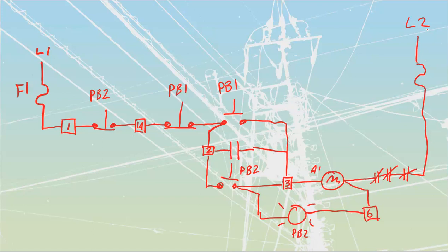We've traced it through. We've gone from component to component. What I would do now is I would say, can I neaten this thing up? What do I see that I can neaten things up? I can move some components around. I have also got a number of wires that are all considered to be the same. If I look at this on my drawing, this wire, number 3, is all considered to be the same wire, right? Doesn't go through any junctions there whatsoever.